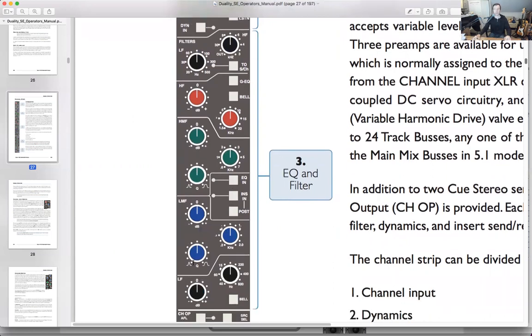The 2 middle bands also have bandwidth, as well as obviously gain and a specific frequency. So you can pick a frequency, for example, here would be 2000 hertz, and you could increase that by what sounds appropriate. You'll notice there's no specifics here. I think this goes up by 15 decibels though. And then you can also adjust the bandwidth.